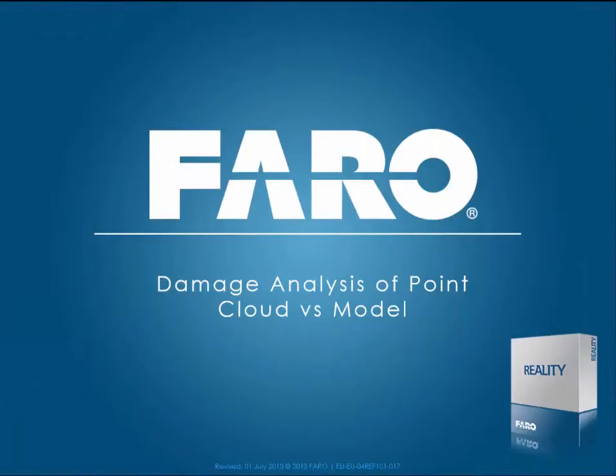Taking that one step further, we've exported the Polo data from FARO Scene as a PTS file. We then bring that into Reality and overlay that data against a model within Reality of a similar vehicle, and then we simulate the level of damage. Whilst at the scene it was estimated that the vehicle was only doing 30 miles an hour, in the software we've proved that by doing the analysis work.